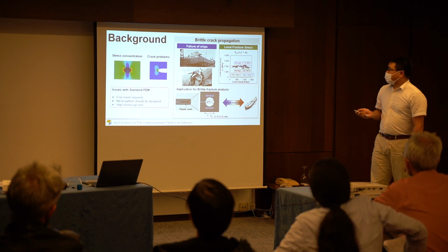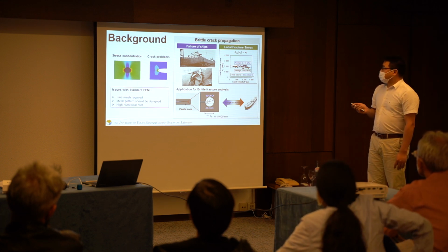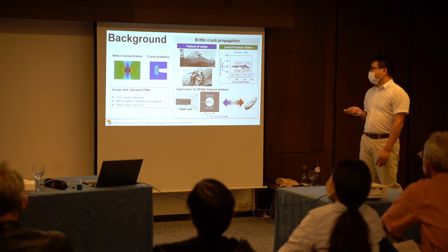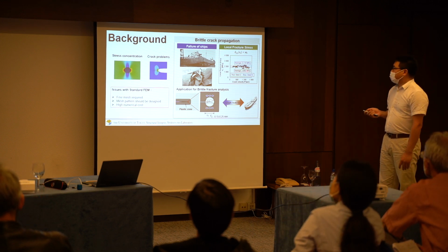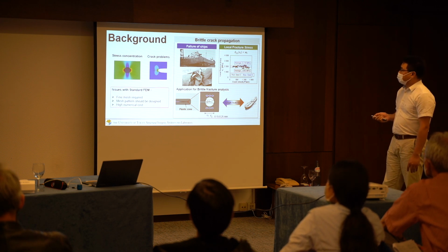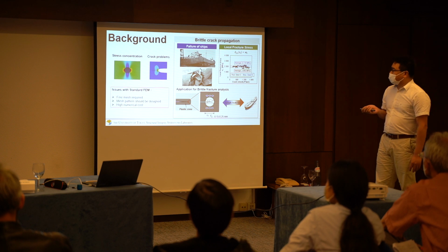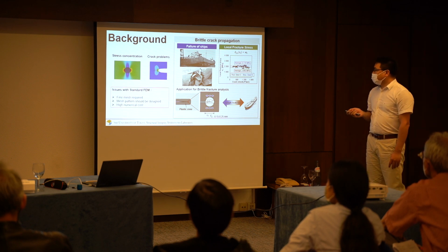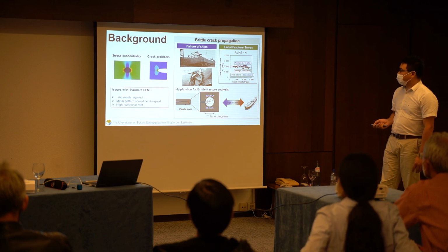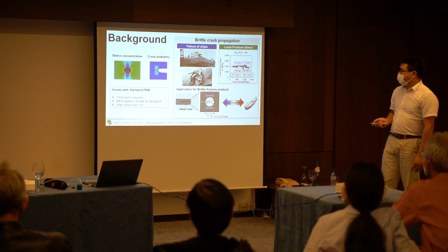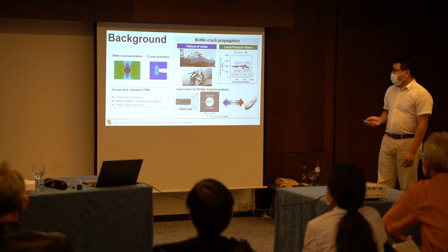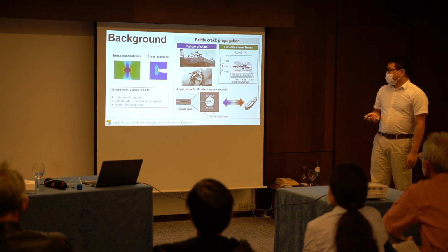RC. At this distance, the fracture stress is almost constant. Here we have some experimental evidence, and we tested two steels, and the value is almost constant. However, the critical length here is in the range of 0.15 to 0.25 millimeters. For the application of this criterion to an actual structure, for example, to a ship, there will exist a scale gap.